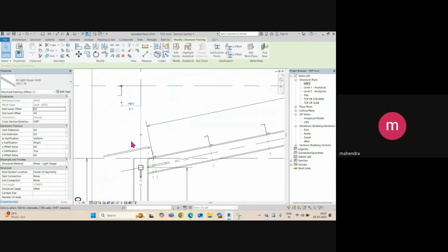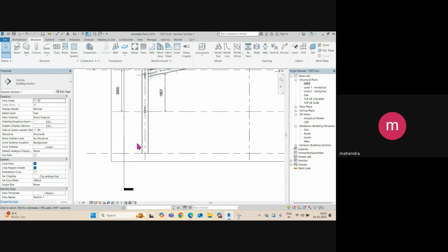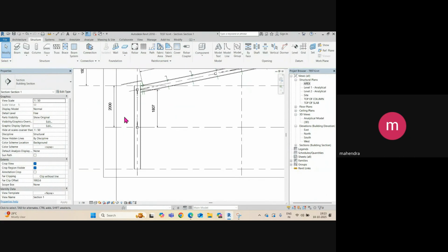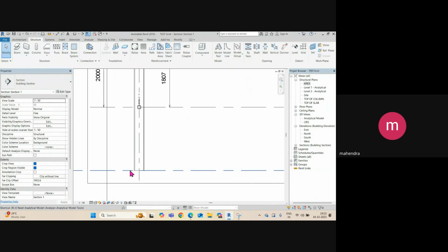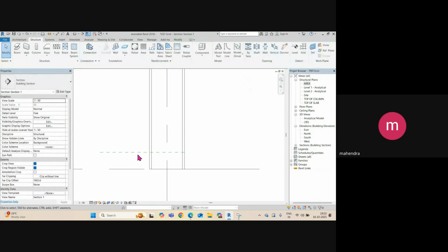Right. Then you need to adjust. Okay. So first of all, you need to calculate how many purlins, sorry, side guards you need to add. So first side guard, I will give here 150 from the top of slab from here. Or you can say 200.